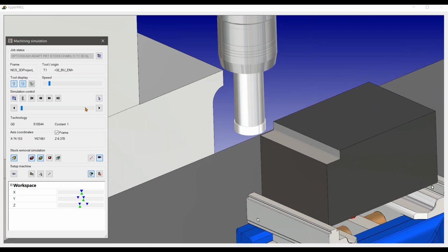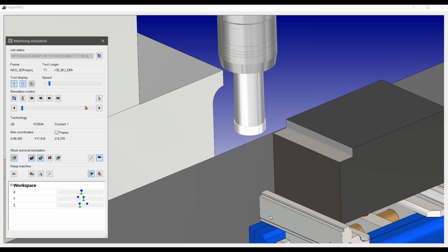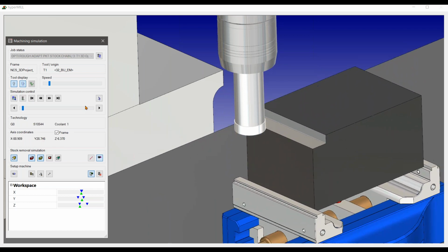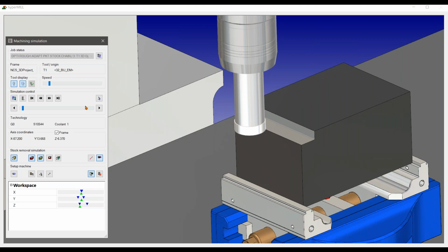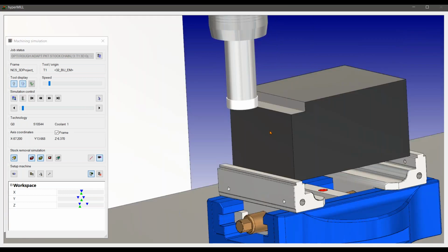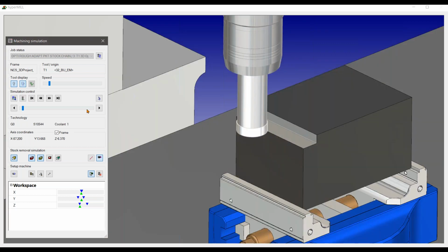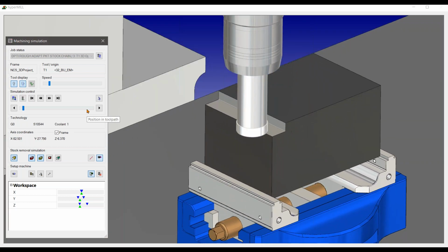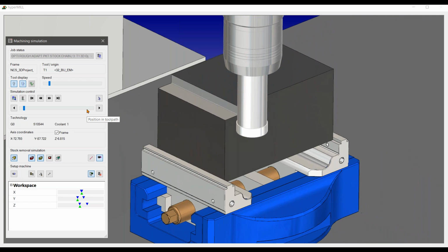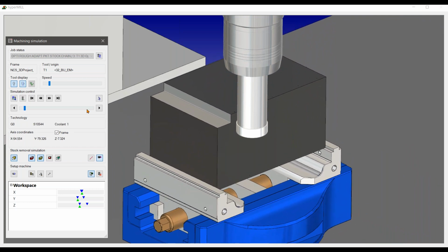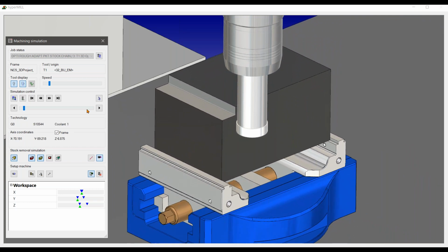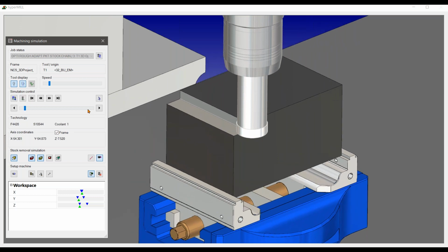Once the tool has left the material and it's performing this arc move and reposition, it's lifted off the material slightly, so you're not going to drag against any material that was left over. This is also done in what we call a fast feed move, which is defined within the cycle. The repositions are fast feed. It doesn't release the machine into full G0 Fmax or rapid mode. It does fast feed, so it's controlled.